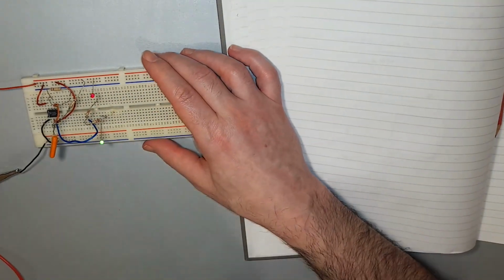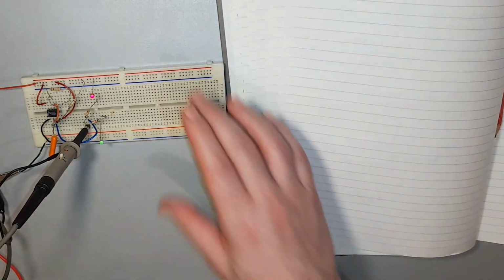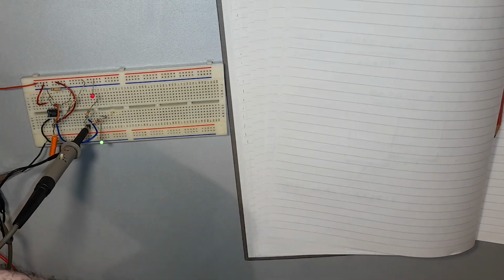Okay, let's see what the duty cycle looks like now. And it works. It works. I think that's working. We have a 5 squares mark and a 5 squares space. It's perfect. Taking up the whole 10 squares of the time base on the screen. And so that is a 1-to-1 mark to space ratio with these 2 steering diodes.